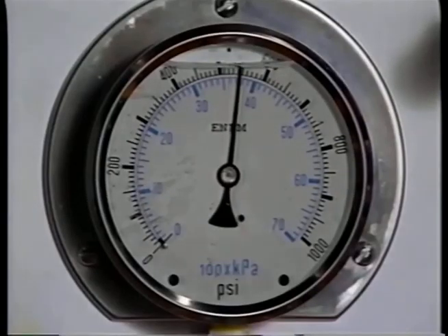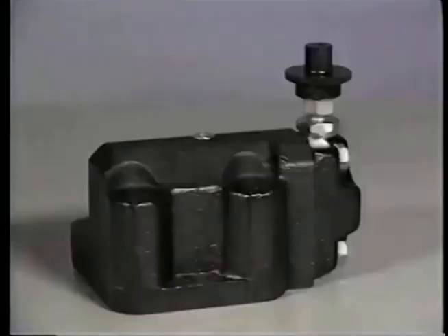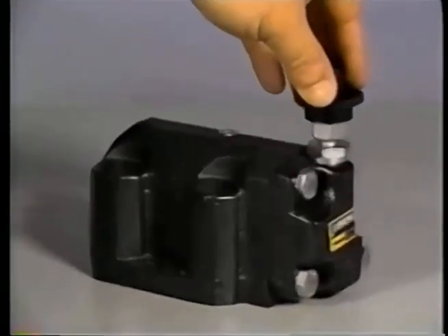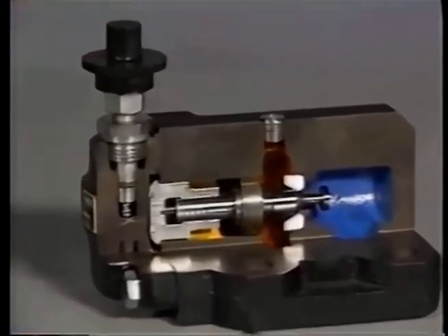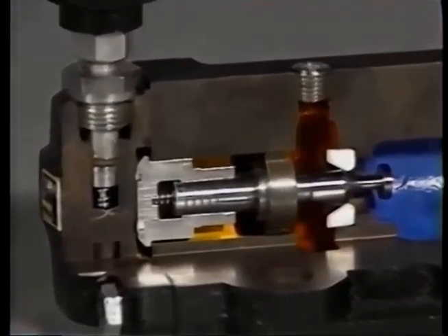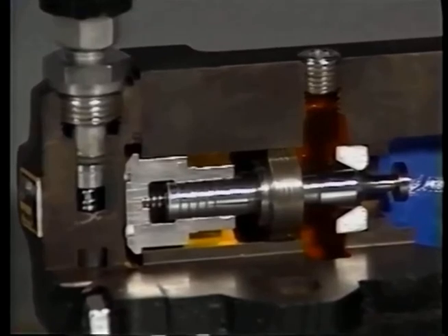Making sure a hydraulic system has fluids of the correct viscosity is important for two reasons. Components like this valve are built with very close tolerances between parts. Fluid with too high a viscosity could not get into the small clearances between moving parts to provide the proper lubrication. The lack of lubrication will cause excess wear and could lead to complete failure of the component.